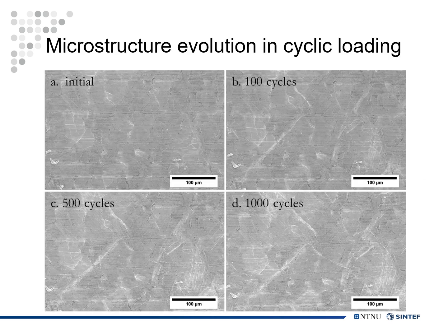The in-situ investigation recorded the real-time microstructure evolution. The deformation was accumulated mainly at the grain boundaries. We can clearly see the deformation bands on the surface of the specimens, and as the cycles increase, you can see these bands becoming better and better visible.